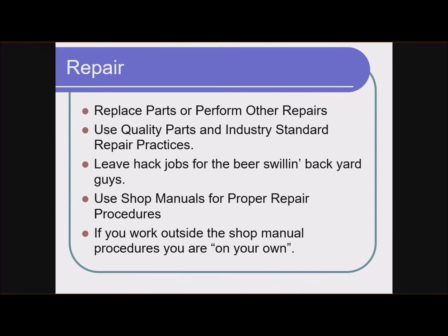The heater hoses didn't feel hot. So, if your heater hoses aren't even getting hot, the heater core is going to be cold. I don't care what you do with a blend door or anything, you're not going to get heat. So I was young, foolish. I went up to Kmart and I bought a thermostat, and I put the thermostat in and refilled the cooling system, bled it, and I'll be damned, still no heat.